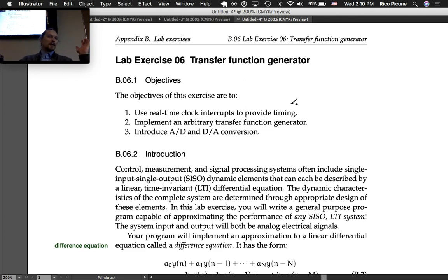If you take too long to do your calculations, you're going to get interrupts before you're done with the stuff you're doing in the loop. So you still have to be careful. You can't do an infinite number of things, obviously, but you can do them without screwing up the timing, which is so nice. You just don't have to worry about that aspect. So we'll learn how to do that. They're interrupts just like the DIO interrupt with the button that we did before, but this one, the FPGA essentially runs this timed loop and just lets you know.